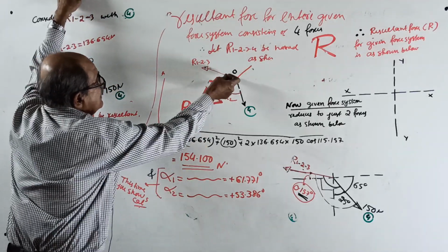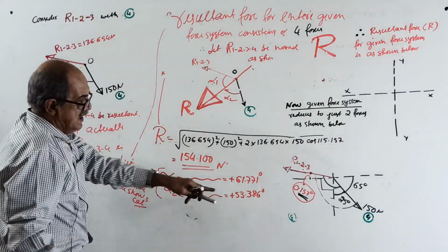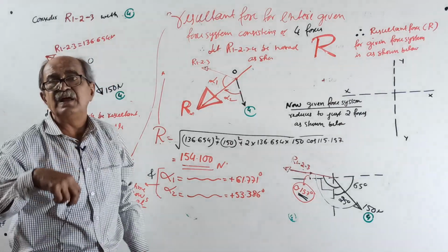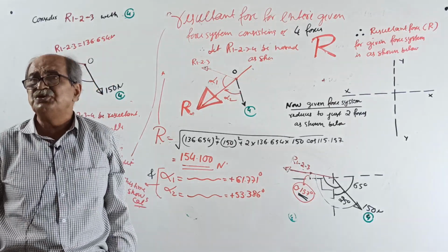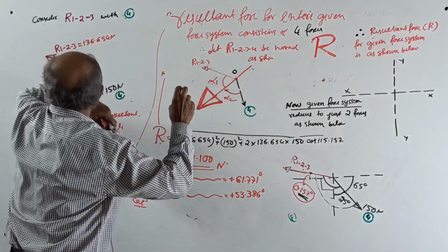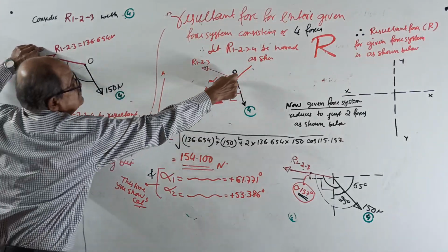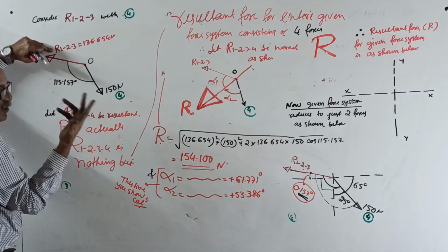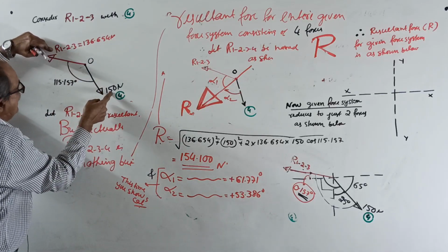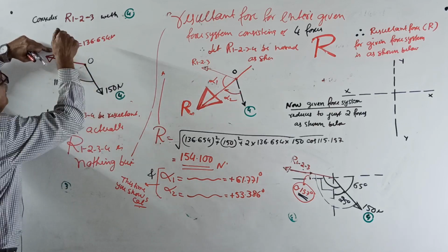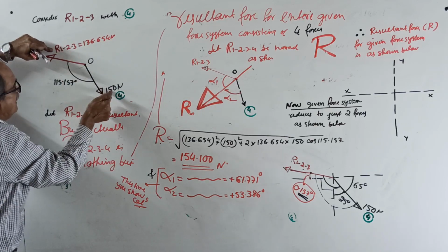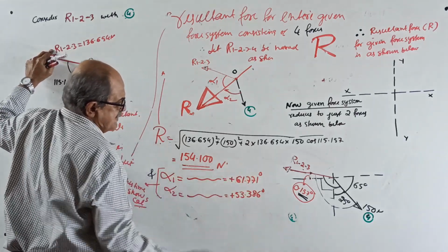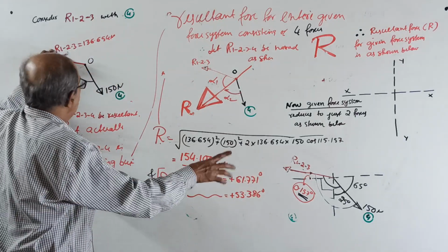And see correctly, this time I wrote the angle as a direct answer. This time you show the calculation, at least do some contribution. Okay, start. The angle made by the resultant, alpha 1, with this force is 150 into sine of this angle divided by this force plus 150 into cos of this angle. You will get 61.771 degrees. I carefully calculated.